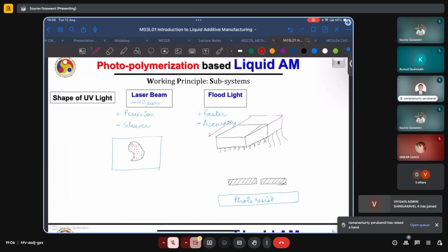The light in this case, as we said, is being shone all over because it is a floodlight. What we want is just this narrow column of light, which is very highly collimated and parallel, to illuminate and cure just this small region as we have specified. But in practice, this will rarely be the case. There will be diffraction of light, and a larger area will be cured than intended. And so we are losing out on accuracy.